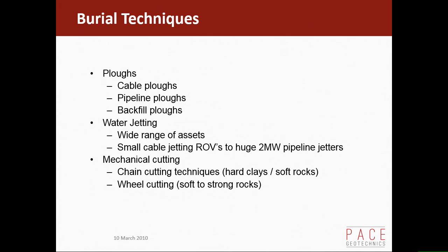And mechanical cutting is there. Really for pipelines, it's chain cutting techniques, hard clays and soft rocks is where they're most effective.